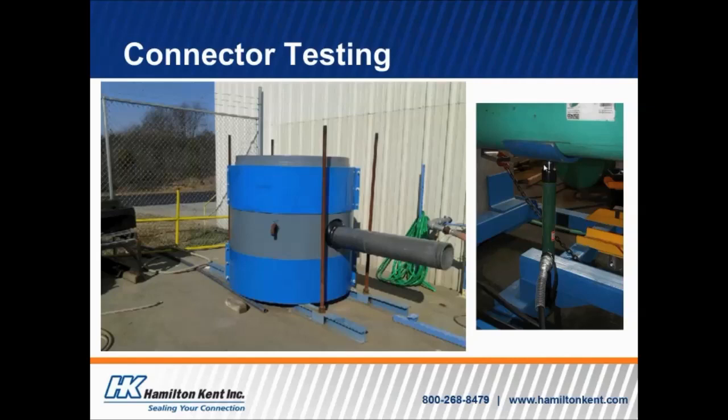So what it does is it's going to be putting upward pressure on the pipe in order to deflect it 7 degrees. In the picture on the left, it's not set up that way yet, but that is what this apparatus is also intended to do. So this is the type of testing that's required for any type of connector that's supposed to meet C923.